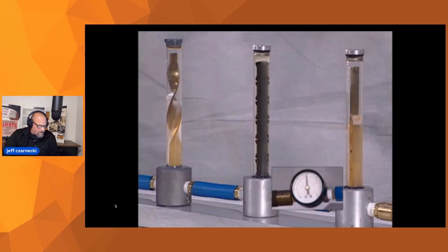Now this video here, it's a bit older. This is available at dme.net, but it gives you some examples where if things aren't installed correctly in a spiral or flat brass baffle, you can get under pressure, you can get the water to blow by or air to blow by, not allowing the water to actually reach the part of the geometry that needs to be cooled. The plastic baffle there in the center is showing you a consistent turbulent flow through the cooling process. In addition, the way that these things are made, we have some fins on the side, so they can be installed slightly undersized to avoid blow-by.